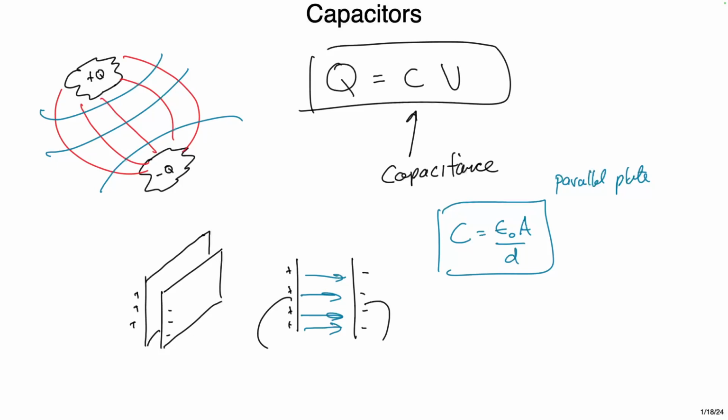It's a piece of conductor, and then there's a thin layer of plastic and another conducting sheet, like aluminum foil type stuff, okay? And then that parallel plate that's held in place by the plastic insulator to keep them isolated from each other gets rolled up, like a burrito. So even though it looks like a cylinder, it's really a flat, parallel plate shape.